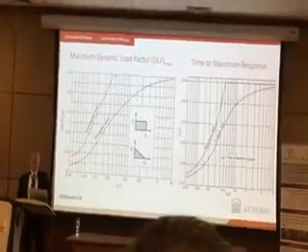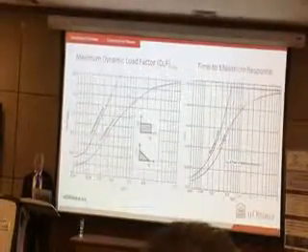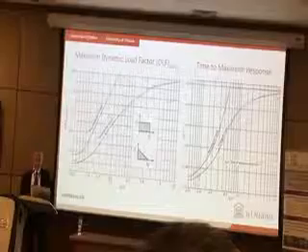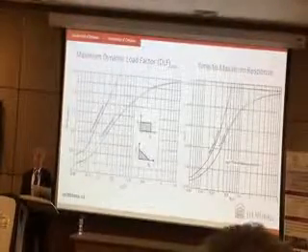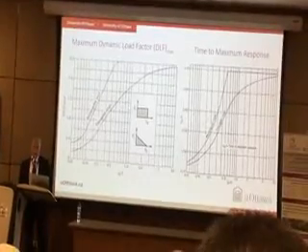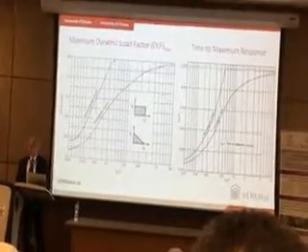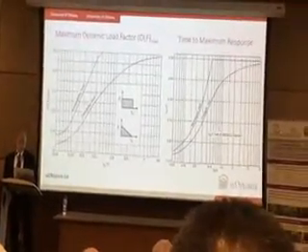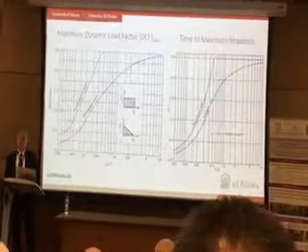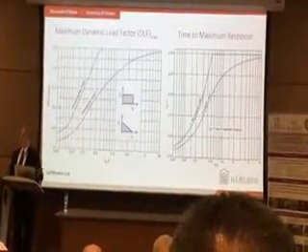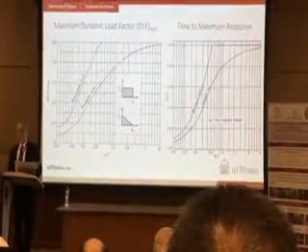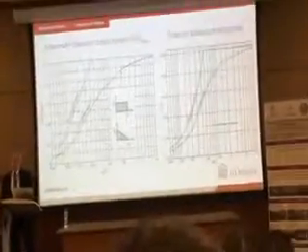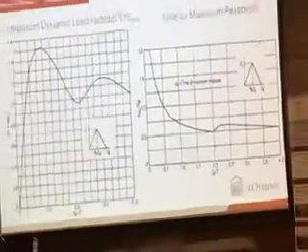So if I know the ratio of duration to building period, I enter here, and my load is triangular load. Why? Because I'm looking at reflective pressure that I already quantified. Then here I get dynamic load factor. It could be 0.8. I find static displacement multiplied by 0.8. It becomes dynamic displacement. It's as easy as that. So dynamic analysis for blast purposes is fairly straightforward.